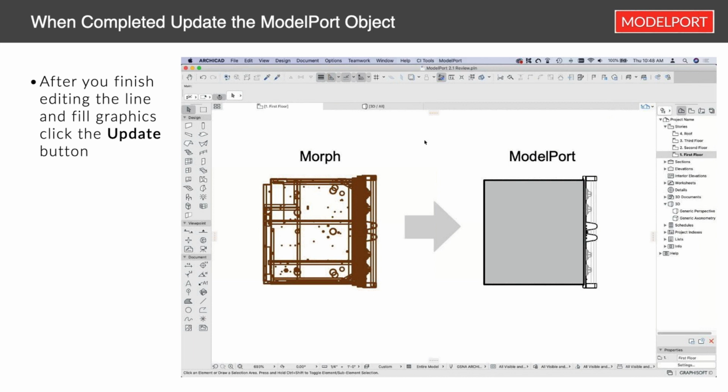So next step I'm going to do is apply this poly reduction. You can see decimation steps down below, showing that we currently have a 32.83% reduction. Now we're going to reduce that a little bit more by typing in 3. Now it's going to a decimation steps of 3, so it's reduced it to 25.6%. Or we can go back up to 32.6%. Again, both are very good.